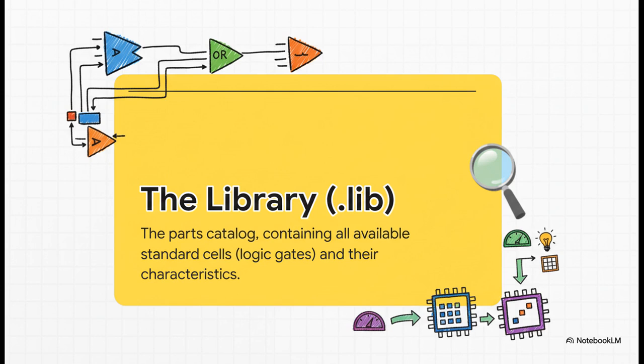The second ingredient is the technology library. You can think of this file as a parts catalog for the synthesis tool. It lists every single available component, every AND gate, every NOT gate, you name it, along with all their specific characteristics, like their size and how fast they are. The tool can't use a single thing that isn't in this catalog.